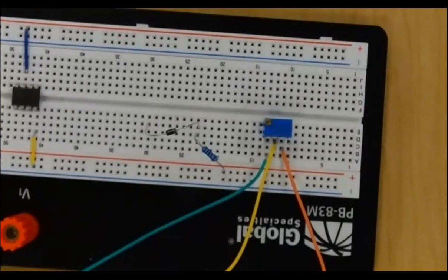For that particular example, where I'm just doing a paper initial design, I'm going to pick something where I'm far enough away from the edges that I'm not concerned about it. What you'll usually do is have some adjustable resistors in your amplifying circuit so that after you get everything built, you can make small adjustments.